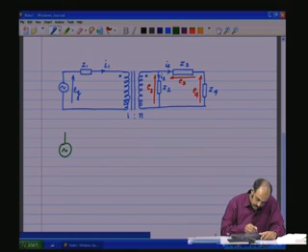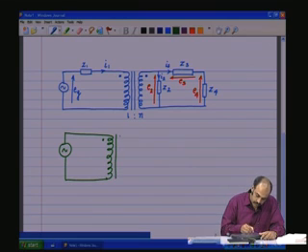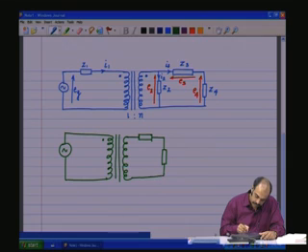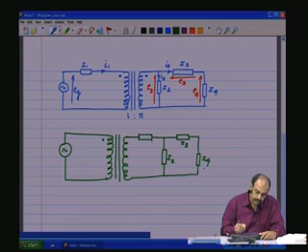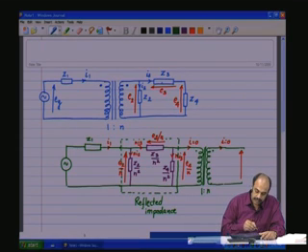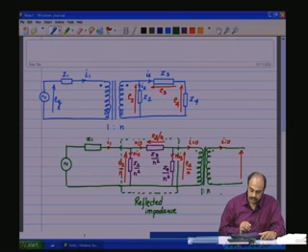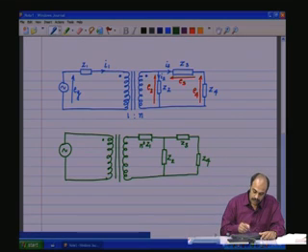So, you get there is an EG, core, secondary windings, and there is an impedance which is shifted from the primary to the secondary, and the rest remains the same. The secondary side impedances remain the same along with the parameters. So, you have Z2, Z3, Z4. Now, Z1 is shifted here, so that becomes n square Z1. Remember that when you shift from secondary to the primary, it is divided by n square, where 1:n is the turns ratio of secondary winding number of turns to the primary winding number of turns. N square Z1,